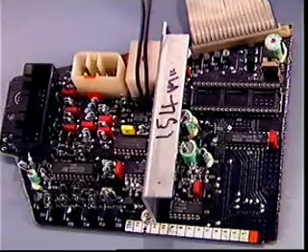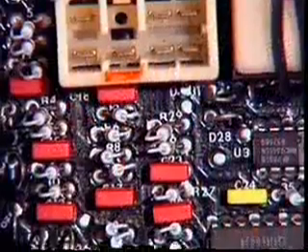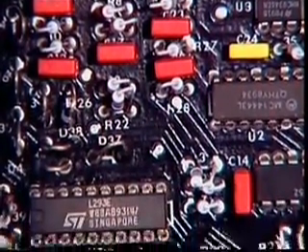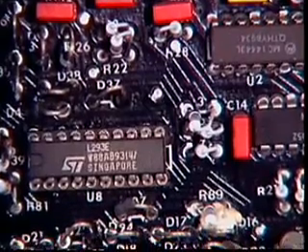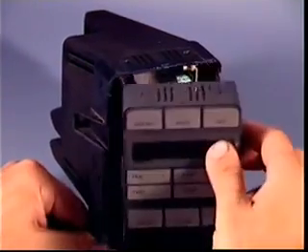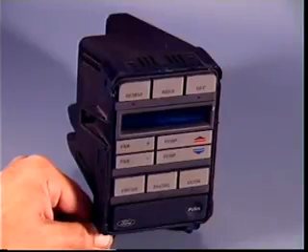occupants. The electronic control unit, or ECU, contains a microcomputer. It is constructed from printed circuitry and has a large number of electrical components and electronic devices. It is normally housed in a metal or plastic container, and on some automatic climate control air conditioning systems, the control panel is part of the electronic control unit.